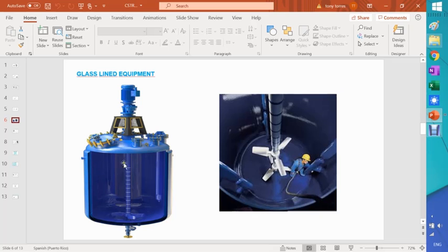So anyway, here's a tank entry. There's a guy here checking the baffle, and there's a huge protocol when there's a man inside one of these vessels. The protocol kicks in, and there are several people involved to get this done properly, with a lot of safety to ensure that this agitator will never turn on while there's a guy inside the vessel.